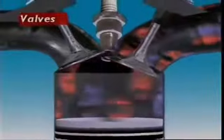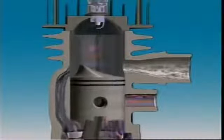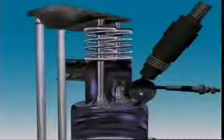This section examines valves. Petrol engines must control the flow of combustible mixture they take in and when it goes in. In small 2-stroke petrol engines, this is done by ports that are opened and closed by the piston skirt during the engine cycle, or by pressure-operated reed valves.